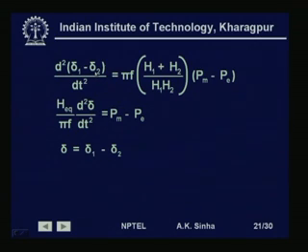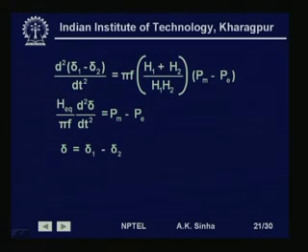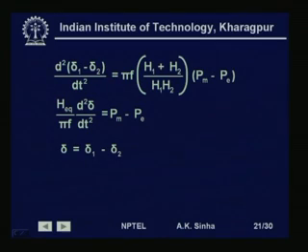After all, we have seen that we used the reference angle as 0, which was the voltage angle of the infinite bus. So, if we take δ2 as the reference angle here in this case, then δ1 minus δ2 is basically the difference in the angle of the two machines. So, this turns out to be the equation which we use for a single machine infinite bus system.